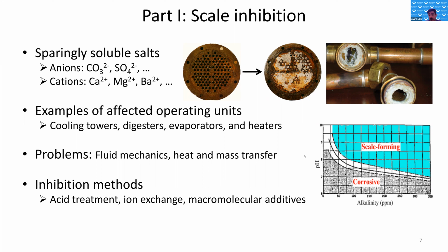So typical treatment of these units is based on acid dissolution of these scales, which in some cases, depending on the type of the scale, the acid can dissolve the scale. However, at low pH, corrosion becomes a significant problem in industries.